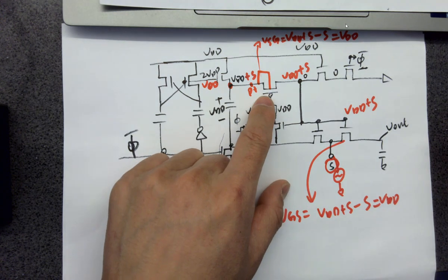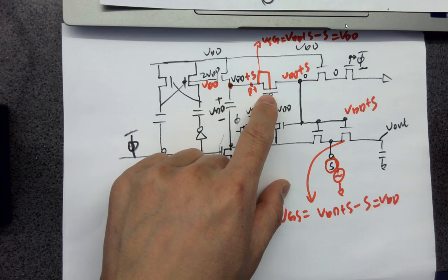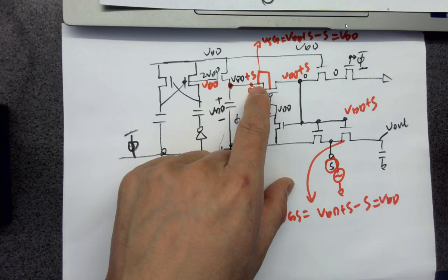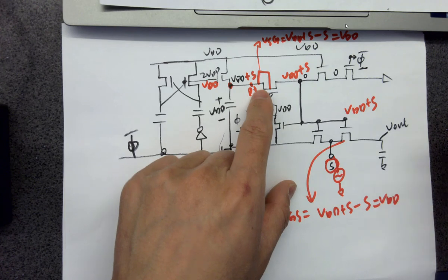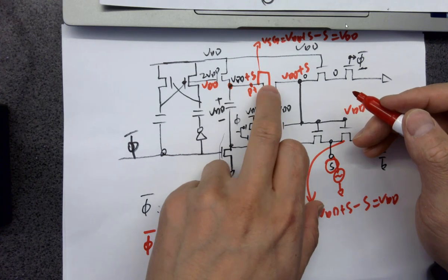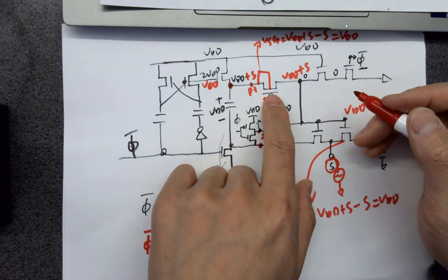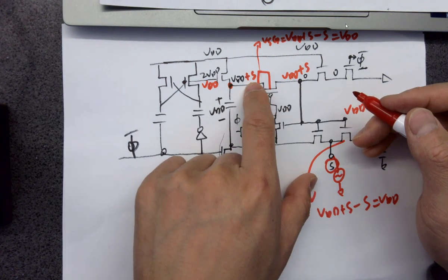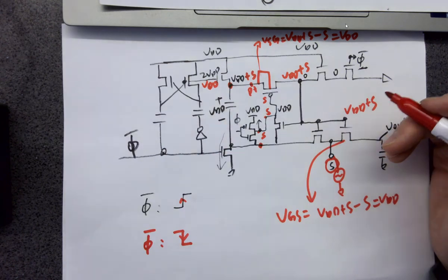You don't have other higher voltages. So the body of the PMOS, or the N plus, or the NWEL, has to be shorted to the source of the PMOS, because that's the highest voltage in the entire circuit. Okay, and it's constant. Whenever the source is getting higher, your NWEL of the PMOS is getting higher at the same voltage, so the PN junction is never getting forward biased.